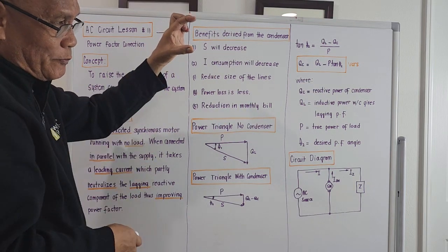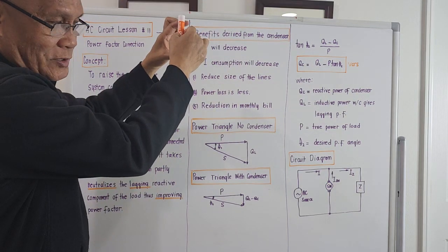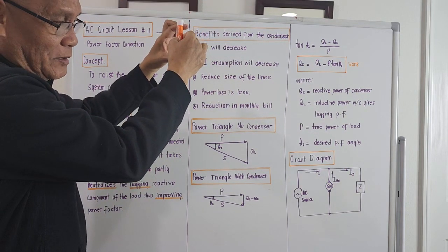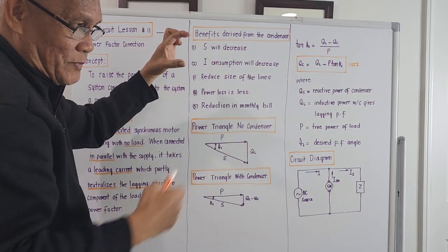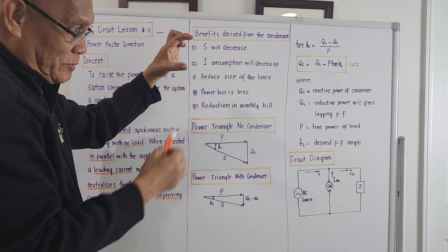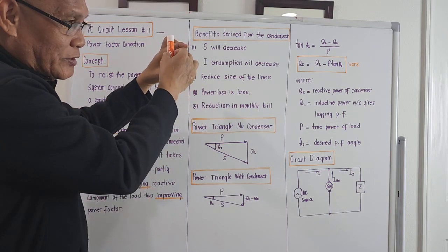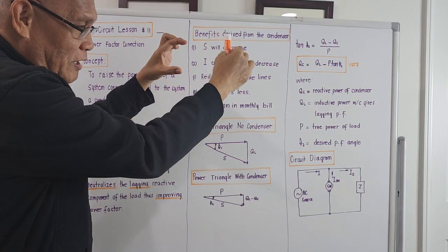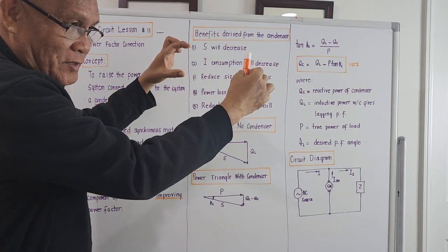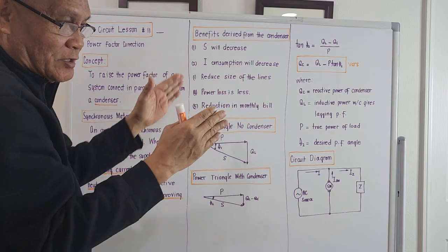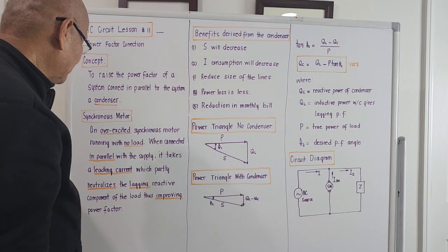To improve our power factor, we connect a condenser in parallel with the utility line, meaning in parallel with the total load of the house or business enterprise. So it seems there are only two loads: the condenser plus the single equivalent of our houses or business enterprise. Their currents will try to interact to improve the power factor.